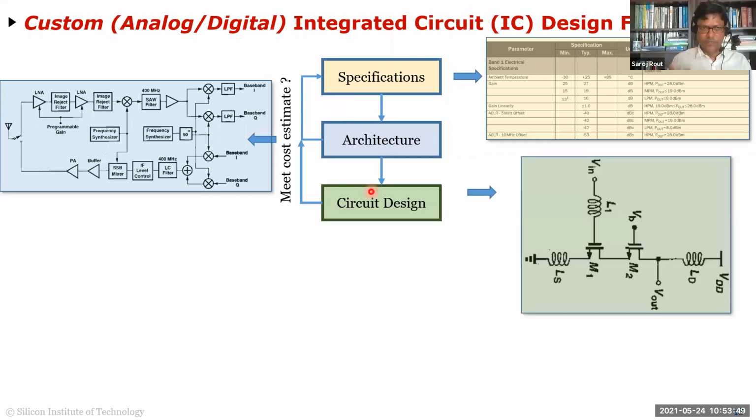Like I said, if you're doing custom circuit design, if I was designing an LNA as a circuit designer, I would just start putting it together. And this is technology dependent in the sense that I need to know what technology I am designing it in. I just can't say, okay, I'm just going to do a source follower LNA with these inductor values and so on, because every technology has different performance transistors, different ways you can make inductors and so on. So I have to choose a technology in full custom analog design.